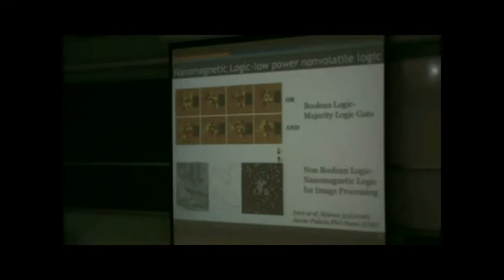So the main thing to show in this case was that we are doing magnetic logic now with the spin orbit torque, which has no magnetic field anywhere. Input, output, clocking, everything is electronic. And compared to what used to be the state of the art, we are 3 orders of magnitude lower in current and 5 orders of magnitude lower in energy dissipation. Before that, if you took the amount of energy you dissipate in creating the magnetic field, you would be almost 6 orders of magnitude away from subthreshold logic.